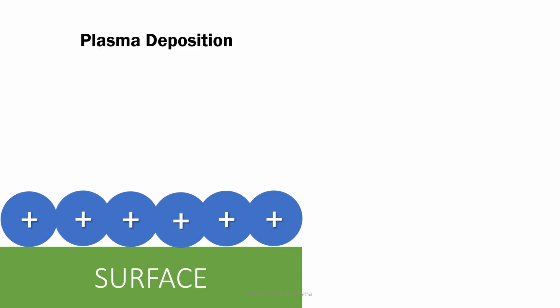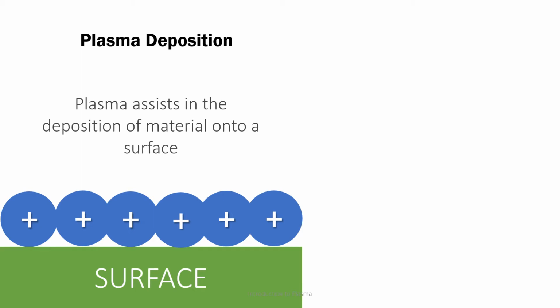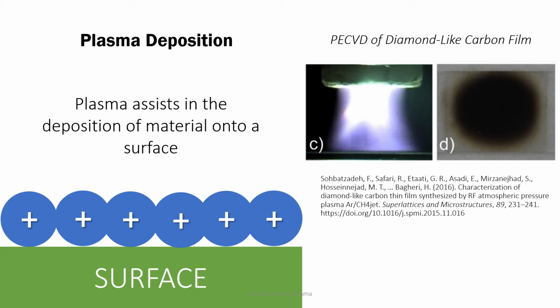Current plasma treatment processes. First, we have plasma deposition. In plasma deposition, we're simply adding material onto the surface of our substrate. There are two avenues for plasma deposition. We have sputtering, in which a target material is impacted by ions, dislodging the target material, which is then deposited onto our substrate. We also have plasma-enhanced chemical vapor deposition, in which we're ionizing the materials to be deposited.